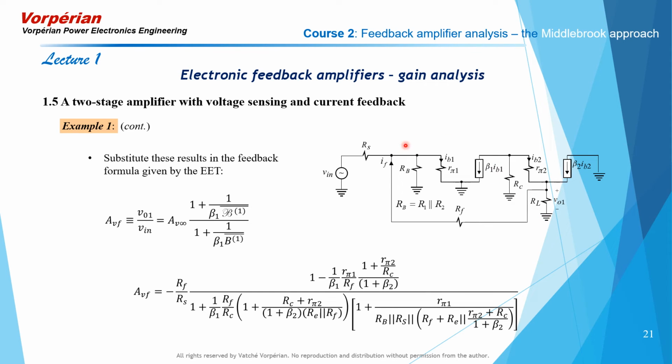So if there's nothing going on here, and the signal goes from the input to the output through the feedback path here, through the feedback connection, I should say, then all I have is a bunch of resistive dividers, voltage dividers, and that's a non-inverting path. The output voltage sign follows that of the input, and it is an attenuation. There is no gain in the system. We killed the amplifier.